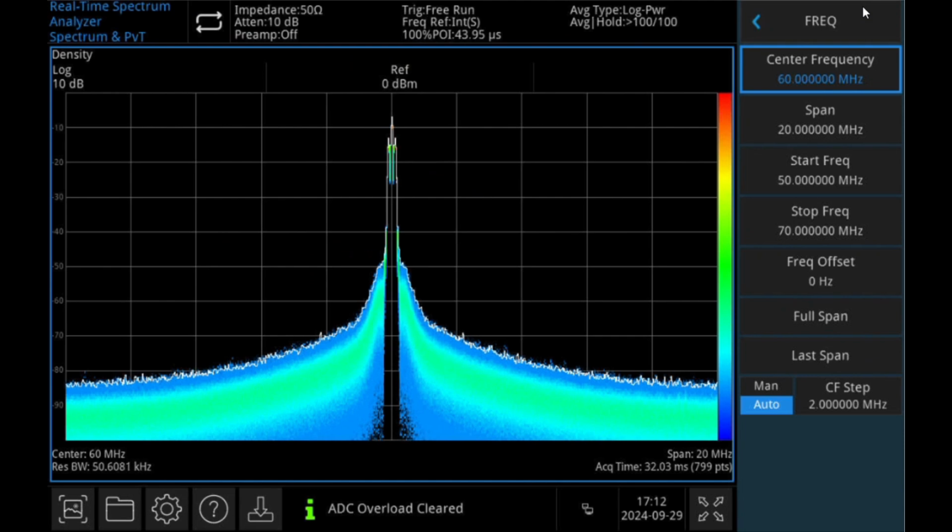In addition to this, real-time spectrum analyzers can also measure wider bandwidth and have higher data analysis and receiving triggering capabilities. It can also measure PVT, power versus time of a spectrum. PVT represents the relationship between power and time.